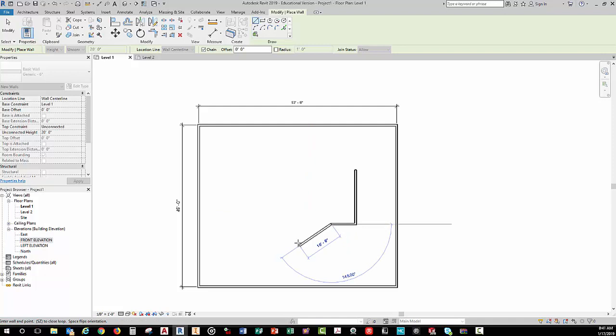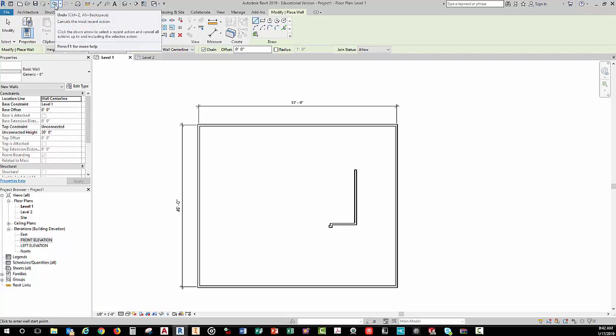And then what if I wanted it to go down 8 inches? Well, I can either do 0 space 8, or I can type in 8 inches. And I always forget to use the inch mark, and I end up making it 8 feet, or I fat finger it and things move. So what do you do when that happens? Well, you can hit escape, and then you can go up here and hit undo, and it fixes things normally. Remember, Control Z is also your escape button.